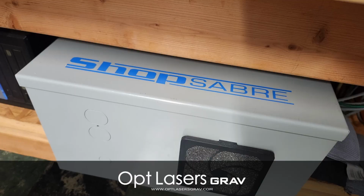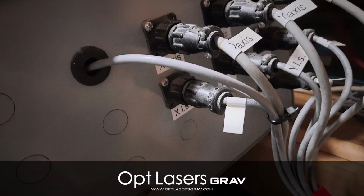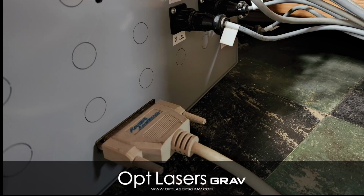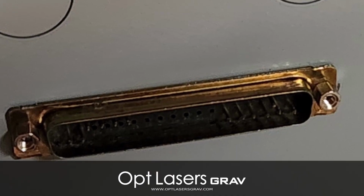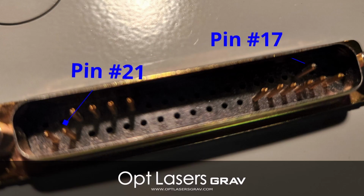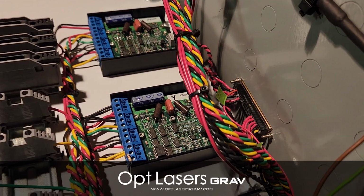Locate the control box. You want to ensure that all power is disconnected from your machine. Then we're going to disconnect all the lines running to the motors and switches. Now let's remove the parallel cable from the side of the control box. Let's take a look at the DB37 with the cable removed. Here on the back side we can see that pin 21 and pin 17 are installed. On your machine, most likely the pins are going to be missing. Let's open up the cover of the box and take a look at this connector from the inside.